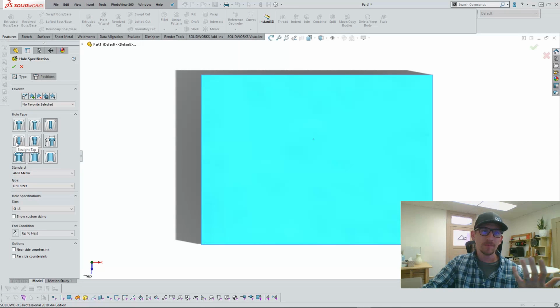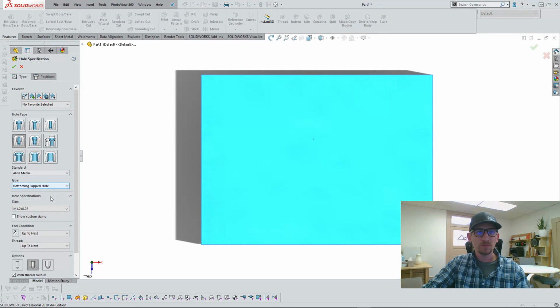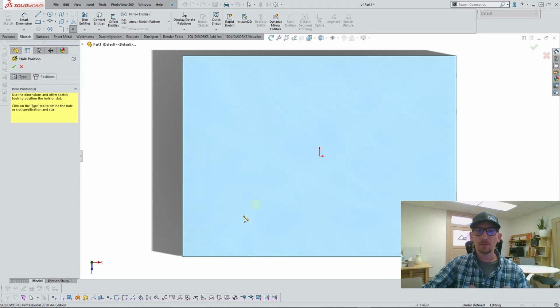So let's, for instance, come in here. Let's do a straight tap, and we'll do bottom tap, and we want to go off on ANSI inch. And then with that, we want to come in and say, let's do quarter 20. Okay, so now after I have that, I need to go to my position tab and drop where I want these holes to go. I know we're talking about doing a linear pattern, but I always like showing a little more than what just the actual feature is.